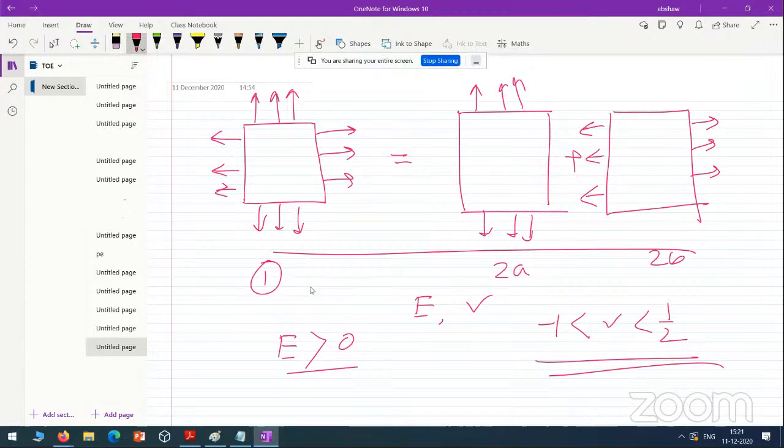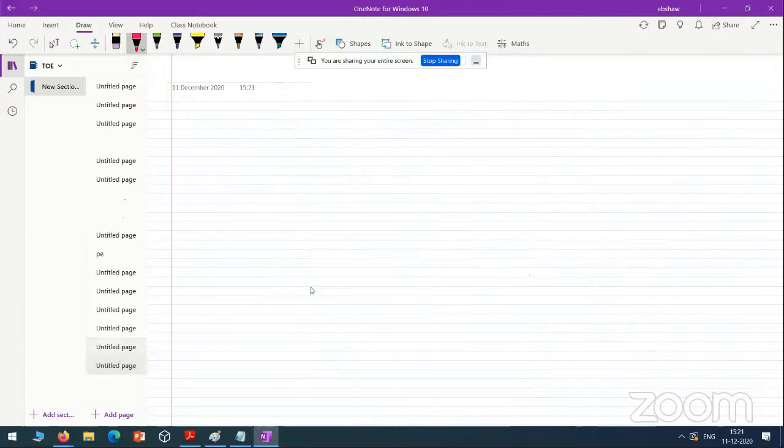So how did we arrive at these bounds? If you recall the constitutive relation, meaning the relation between stress and strain in a three-dimensional body, we have 6 stress components, 3 normal stresses and 3 shear stresses, and 3 normal and 3 shear strain components.